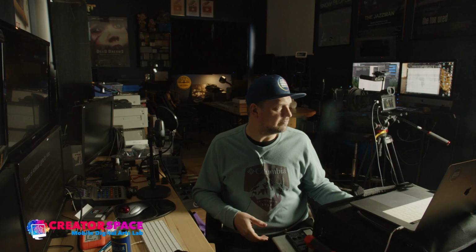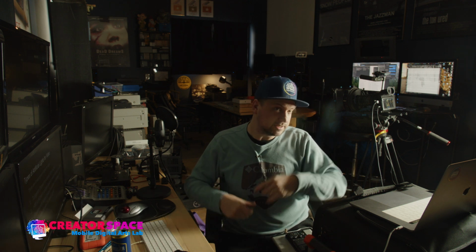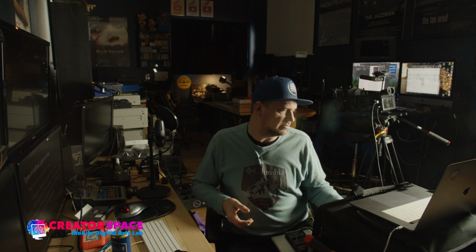So this is the same idea. We get onto a location, there's light bulbs, you're like, I'm going to take this light bulb out. If it's been on, let's say for days, it can be very, very hot. You can burn your hand. So make sure you turn it off, understand that it's cool, or wear a glove. Some sort of a work glove can be sufficient to handle the hot bulb of a tungsten bulb. So make sure you do that.